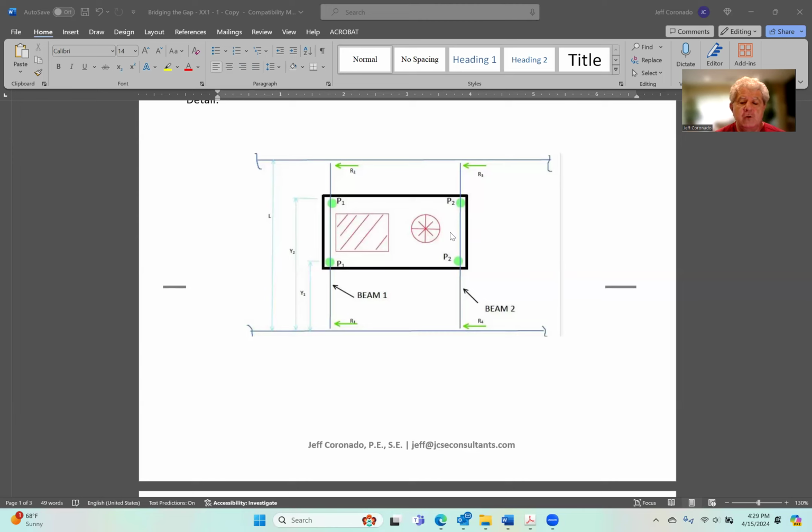In all likelihood, two of them are equal. That's why we're representing both of these as P1, because there will be an axis of symmetry along the longitudinal axis, which is what we previously said. That's why P1 and P1 are the same here, likewise with P2 and P2. The totality of the four corner weights will get you the total weight of the mechanical equipment.